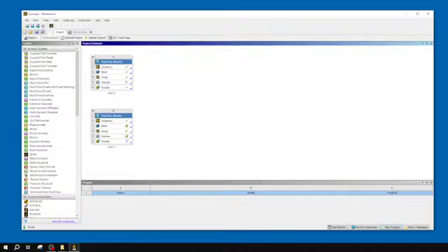These results will have the same display options that I just defined before as I was going through my 0 angle of attack. So yes, that's the big advantage of using Workbench. Quite a long process to get your first iteration, first angle in this case, running, but it makes it very convenient for my subsequent angles where I just have to duplicate these a bunch, change that one factor in my geometry, click update, and it'll run through all my different variables.